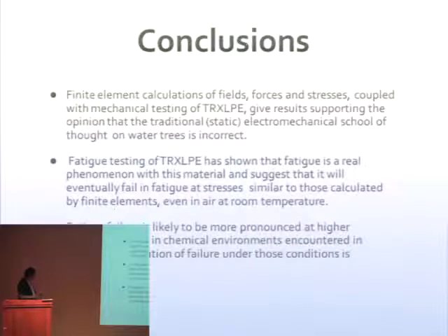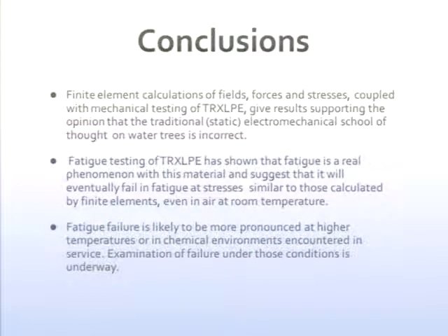So my conclusions are that finite element calculations of fields, forces, and stresses, coupled with our mechanical testing, give results supporting the opinion that the static electromechanical school of thought on water trees is incorrect. The stresses that are developed electromechanically are not sufficient, we believe, to break the stuff under static conditions. But we don't have static conditions in these cables. Instead, we have fatigue conditions.